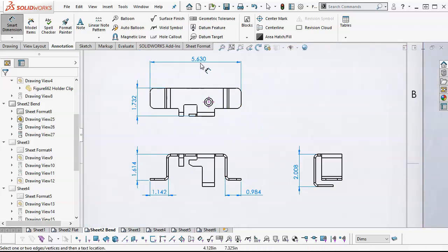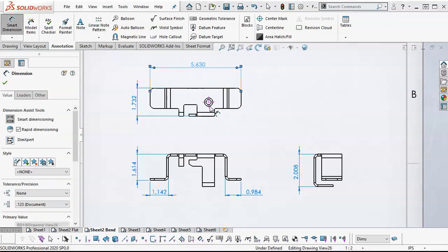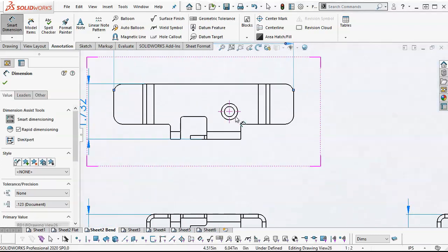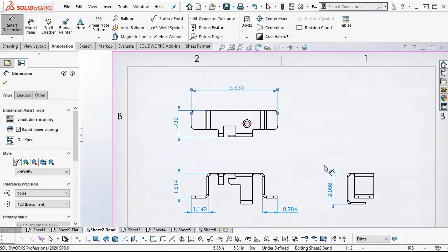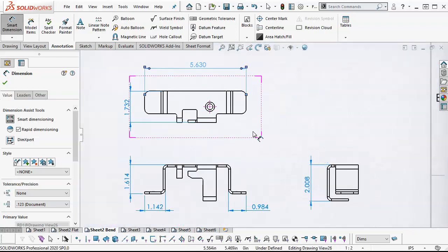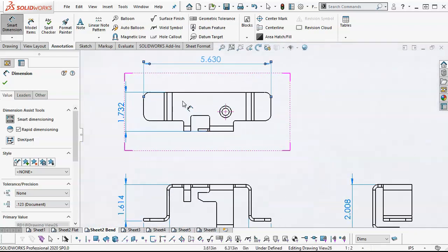And then the hole locations, if I was going to bring out some GD&T, I'd want to do kind of a positional tolerance study. Which of these is critical? What's going through? How much can this smaller hole float if the larger one is the more critical? How much can the larger one float if the smaller one is the more critical? What is it aligning to create our geometry?